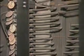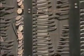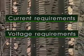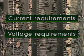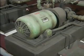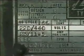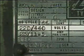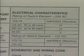In this part, we'll examine characteristics of a circuit that affect the types of conductors that should be installed. We'll see how to determine the current requirements and the voltage requirements of a circuit. Every circuit has basic current and voltage requirements that are determined by the equipment that's connected to the circuit. Identifying these basic requirements is sometimes as simple as reading the information directly from an equipment nameplate. In other situations, you may need to refer to manuals or maintenance materials that provide current and voltage information.